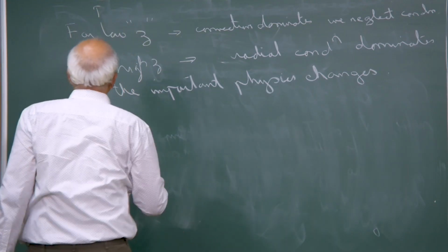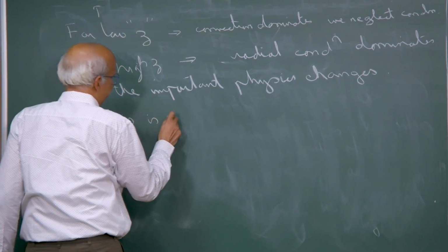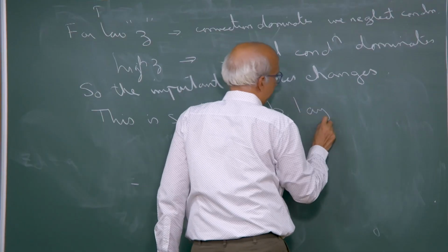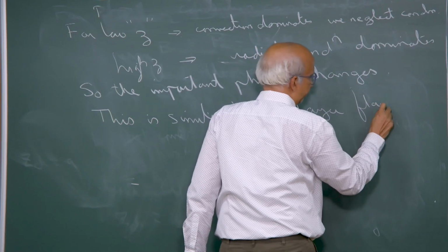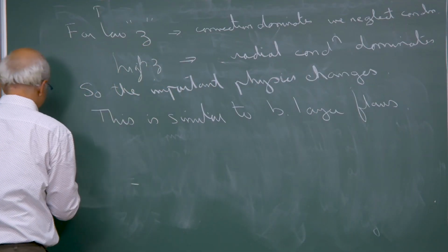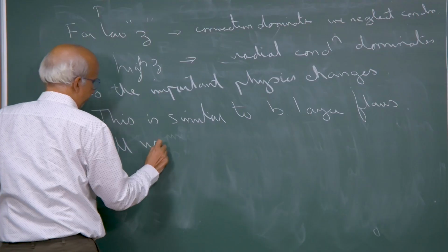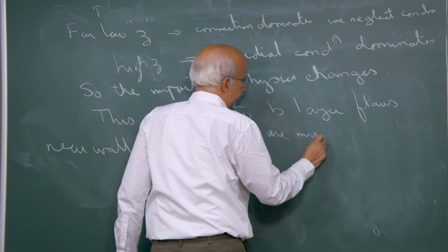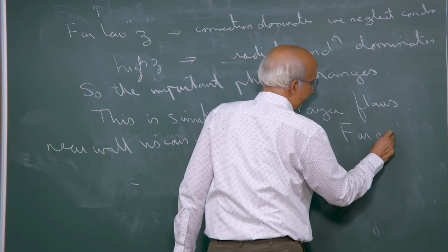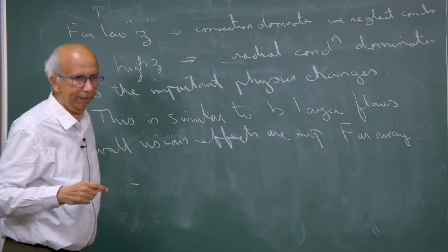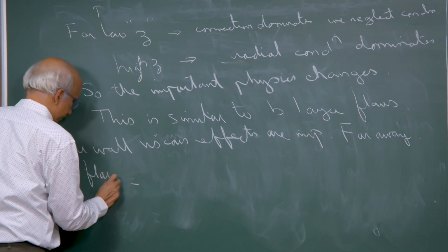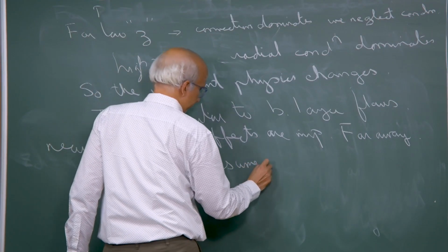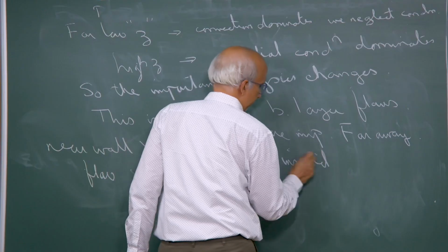You assume that the far upstream velocity u infinity prevails everywhere and neglect viscous effects. So there are many problems like this, similar to boundary layer flows. Near the wall, viscous effects are important; far away, the flow can be assumed inviscid.